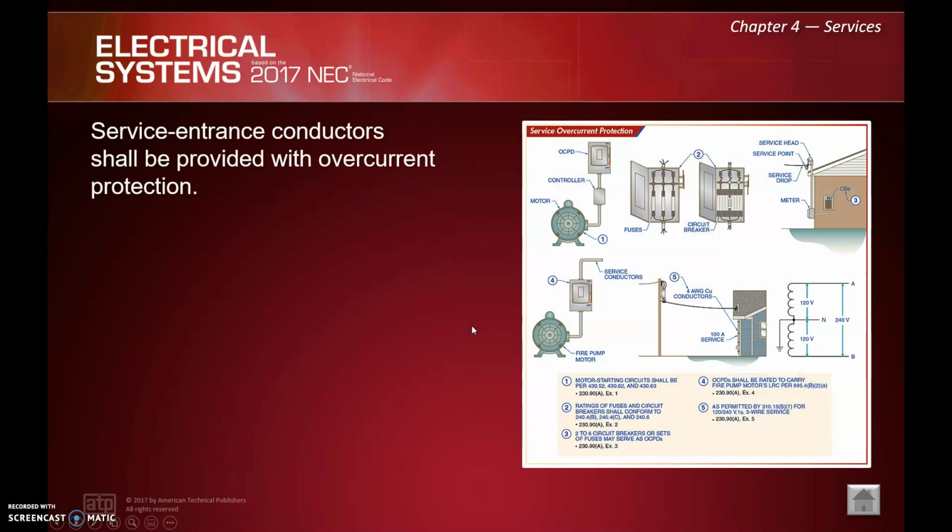Service entrance conductors shall be provided with overcurrent protection. Again, that's another big reason why we can't run those service entrance conductors inside the building before we hit our service entrance disconnect, because that's where we get our first means of overcurrent protection, right?